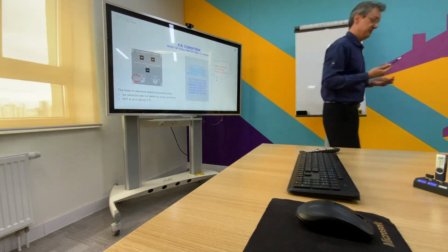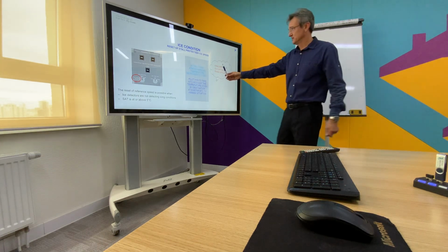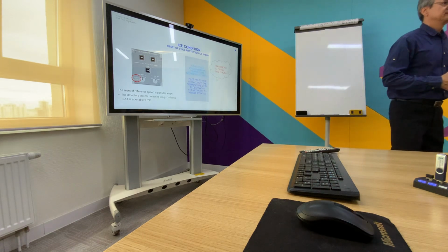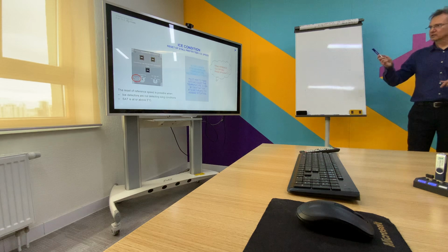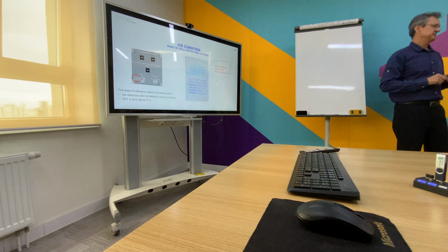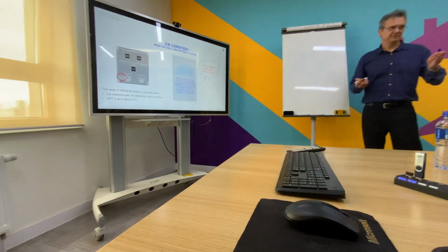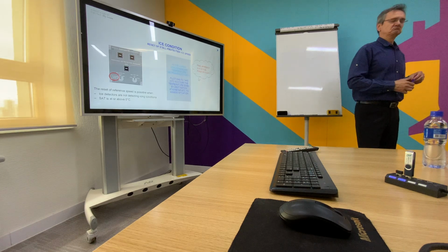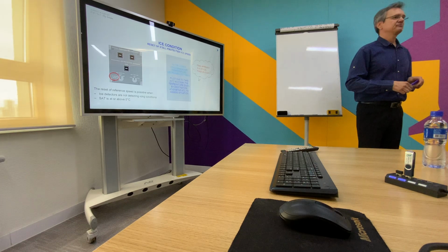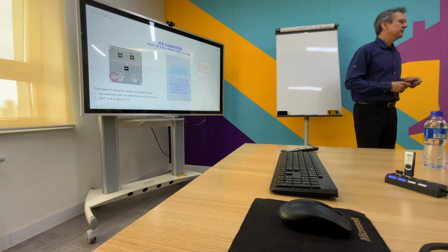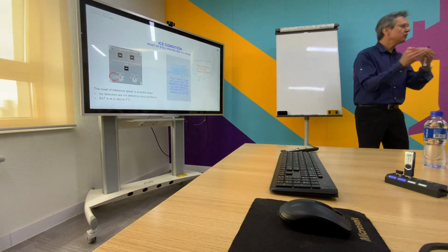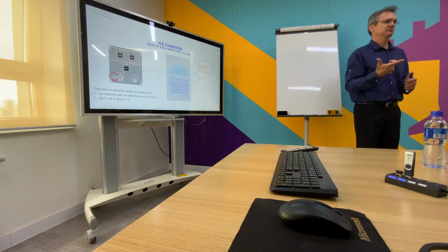My suggestion, remember that we have these rules of thumb. For every 1,000 feet, the temperature decreases 2 degrees Celsius. So if I have in the ATIS 7 degrees, I calculate for ice speed, so as not to be worried on the final approach, on the short final approach, to reset the speed. You know what I mean?